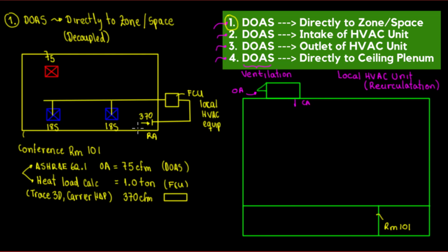Let's check. From here, from the HVAC unit, you're going to have a main duct and you're going to have the branches. So for example, this is my main duct. From the main duct, I'm going to tap out a VAV system right there. I need a terminal unit. So for this, I'm going to put in a flex right here. But before that, I'm going to just do this. Just bear with me a little bit, and there we go. I'm going to put in here a flex.